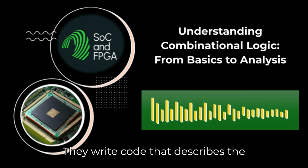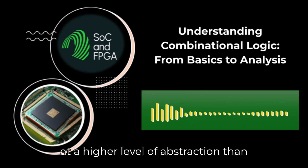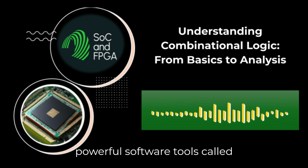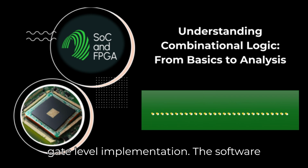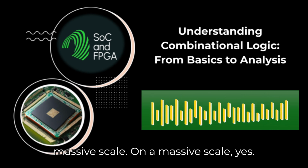They write code that describes the circuit's structure and behavior, often at a higher level of abstraction than individual gates. Then, powerful software tools called synthesizers take that HDL code and automatically generate an optimized gate-level implementation. The software does the K-map work, essentially, but on a massive scale. On a massive scale, yes.